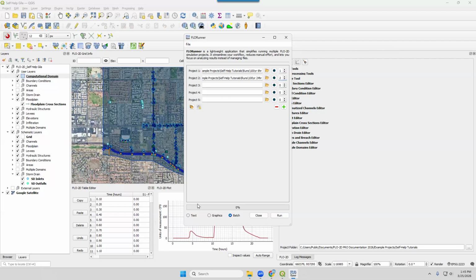And then when you start the modes, you get 2 things. This information gives you not only percent full, but it kind of tells you where you're at in the summary.out. I don't want to run it because I don't want to mess up all my results, but it'll move forward in time and allow you to run and tell you how much of that run that it's currently on is complete. It reads the summary.out and reports it right here.